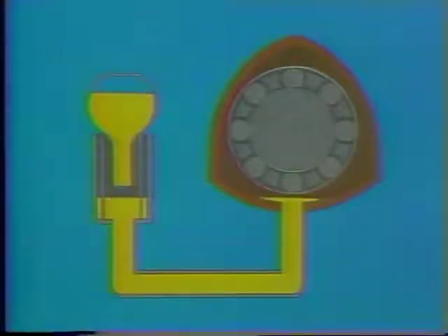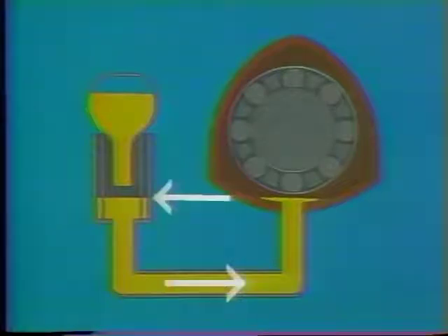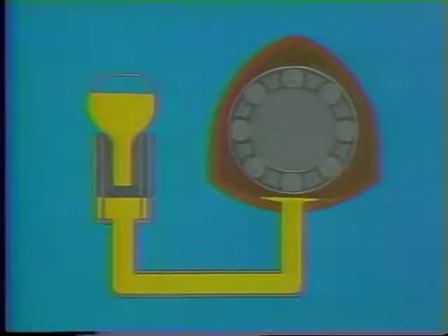As the level of oil in the housing drops, oil begins to flow through the tube into the housing. This causes the level in the oil cup to drop. The oil continues to flow until the levels in the cup and the housing are the same. When the level in the oil cup falls below the opening in the bottom of the reservoir, oil flows from the reservoir into the oil cup. The flow stops as soon as the level in the oil cup is up to the bottom of the reservoir. When this happens, the oil in the housing is back to its proper level.